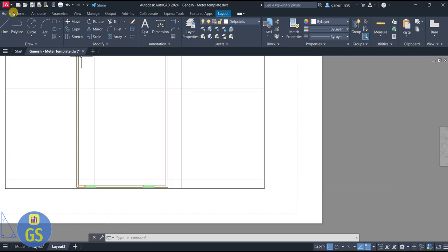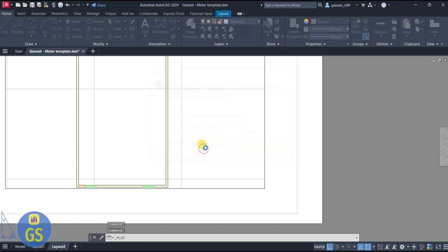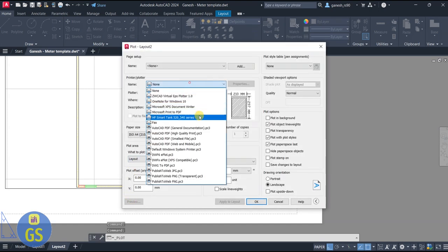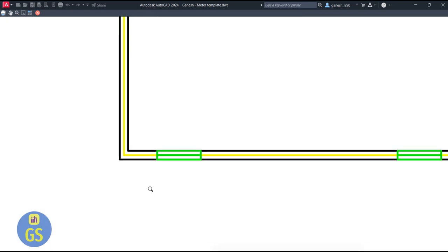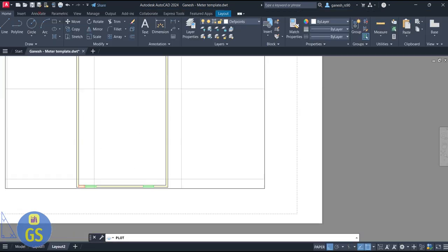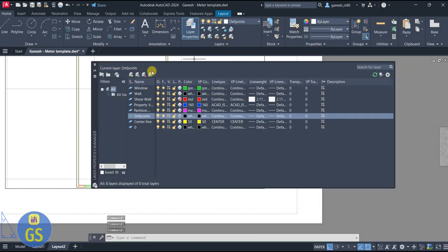Just close it again. Just go back. Again you can see the printout. Go for preview PDF. Right, now see, it's not showing in the printout. Because I turned off the layer's print option, it's hidden, so nothing is visible in the printout. So this is how we can use all the various tools available in your layer manager, and it is very important for civil engineers and architects when you are making building plans.